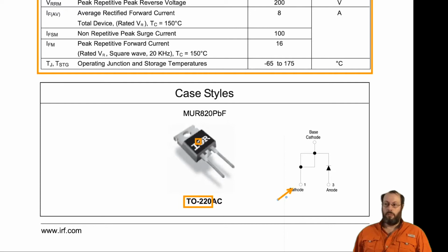Pin 1 is the cathode, which is physically over here, and pin 3 is the anode, which is physically the third pin over here. Now the second one is actually not even noted here because it is shorted. On the physical device, you can see the short actually over here, and in the circuit diagram, it is indicated here.